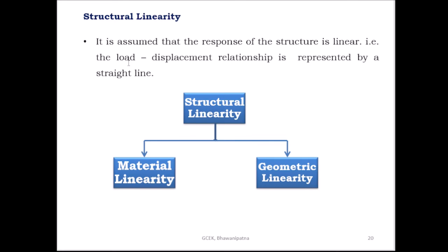Here I would like to say, in a linear structure, the stresses developed in it are within the elastic limit, and in a non-linear structure, the stresses developed in it fall in the plastic or non-linear zone. Such a classification is based on behavior of material. In material linearity, the material obeys Hooke's law, that is, the stress and strain both are directly proportional and represented by a straight line.